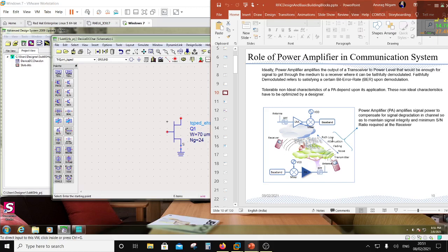Again, if you go to the 60 gigahertz band, 60 to 66 gigahertz, you are going to see an oxygen absorption band. So this is an attenuation due to absorption. So one is due to path loss, the other is due to absorption. And the third one is, let's say you transmit a signal from a transmitter to a receiver and it bounces off various objects in between and reaches the receiver in different phases, and in some places it is going to add up and in some cases it's going to subtract. Now what happens in this case is that in some places, or at some frequencies, you're going to see fading of the signal, right?